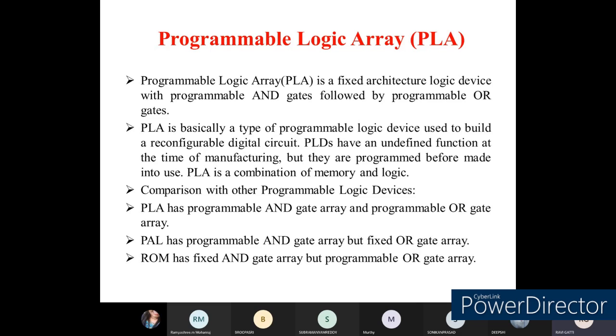So you are going to write the truth table. Based upon the truth table, you are going to do the K-map realization for the 3-bit parity generator. You are going to do the Boolean simplification if any is possible from the truth table. After the simplification, you are going to implement it in terms of circuits, so you go for the synthesis.